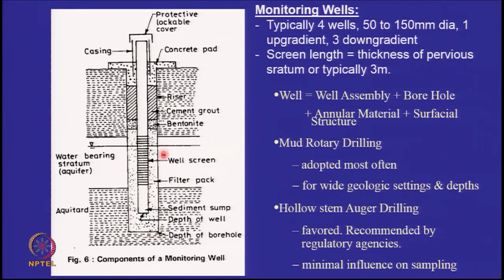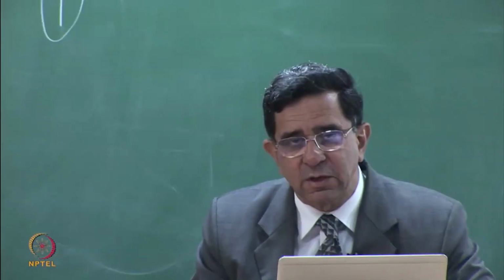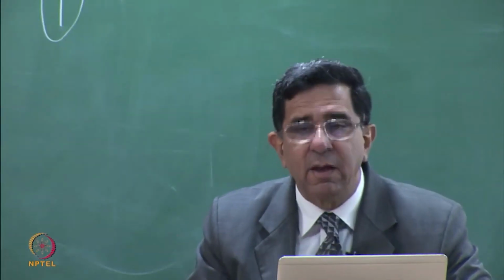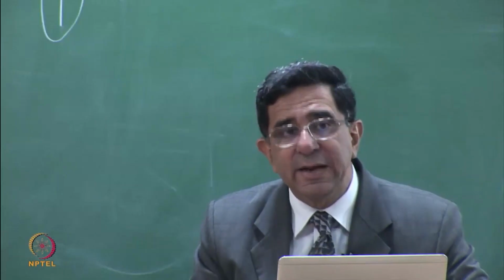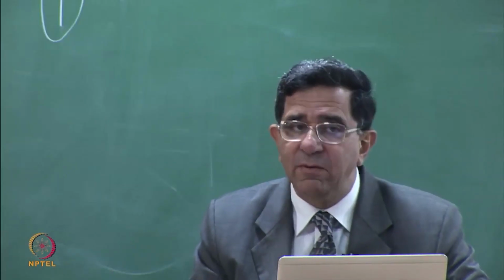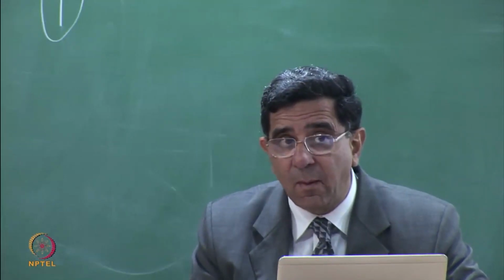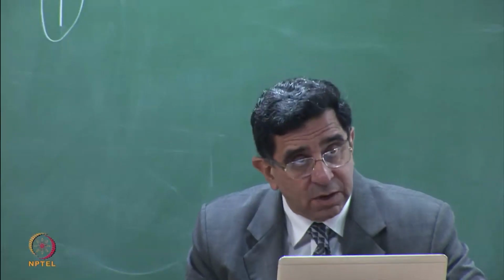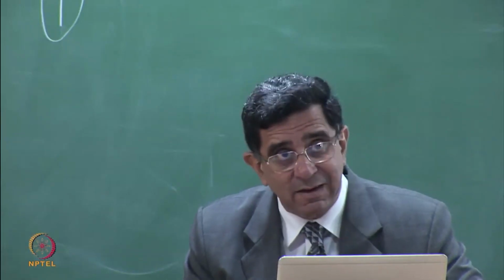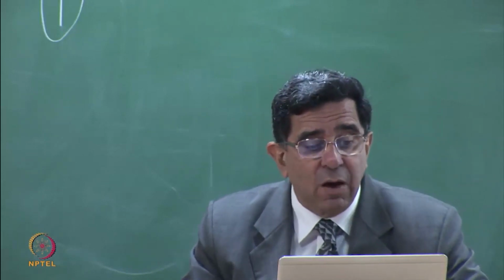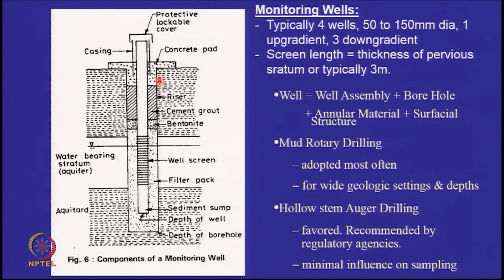First you make the borehole. How do you keep the borehole open? In soil mechanics, how do you keep a borehole open? Most of the time we don't use a casing. Yeah, so don't give the answer in an inverted way. We can use a casing if you are going very deep, but if I am not going very deep, I will use bentonite. And if I am using wash boring, then the drilling fluid is bentonite slurry. It keeps the borehole open. So now you've got the borehole which is open, which is full of bentonite slurry.